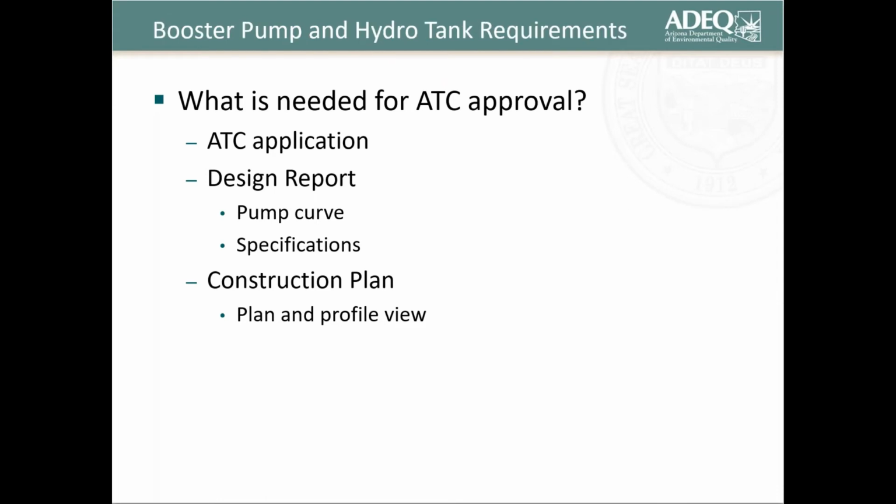And now we'll look at the booster pumps and hydro tank requirements. So again, back to that ATC application, make sure it's completed for that type of component. And then the design report, we're looking at the pump curve, which is usually provided with the manufacturer manual. You can take that, include it in your report, just explain it in detail.